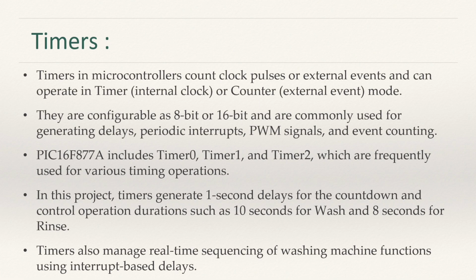Timers. Timers in microcontrollers count clock pulses or external events and can operate in timer mode, using the internal clock, or in counter mode, counting external events. They are configurable as 8-bit or 16-bit and are commonly used for generating delays, periodic interrupts, PWM signals and event counting.